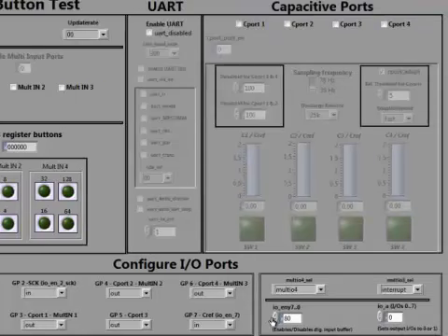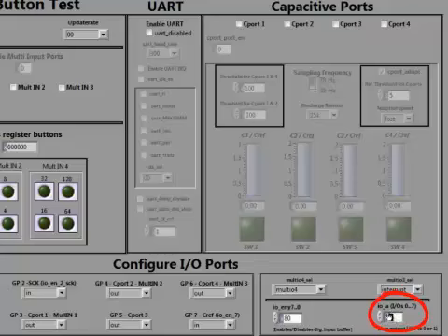When a pin is configured as output, the state of the output pin is controlled by the respective bit in this box. For example, if GPIO 6 is configured as output and if the state of the bit should be 1, then this box here is set to 40 hex. If the bit should be set to 0, then this box must be set to 0.